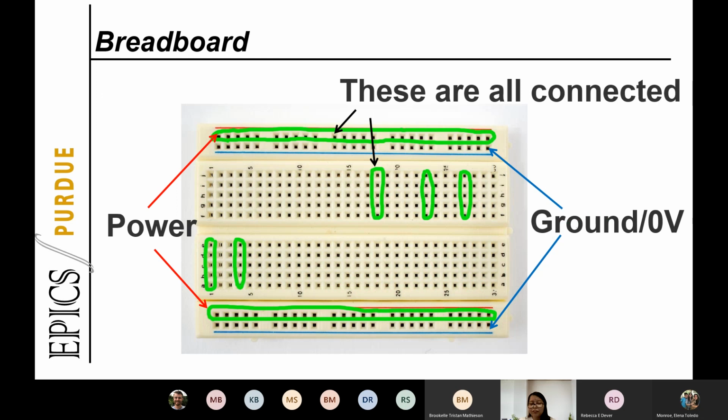And then the last portion for this introduction class will be the breadboard. A breadboard is basically where we connect all these elements, all these passive elements, and that's where we measure current and voltages. These breadboards are very similar to what we have in lab. The main portion here is the power, where we connect the positive and negative polarities of a battery, let's say. And we can connect it in these extremes here or on the other side also.